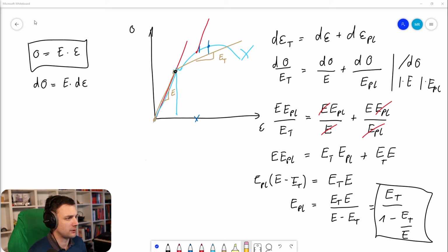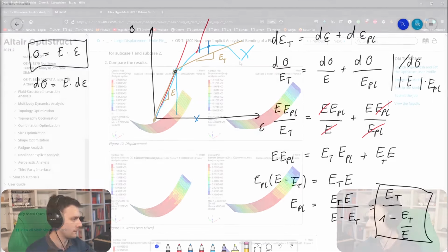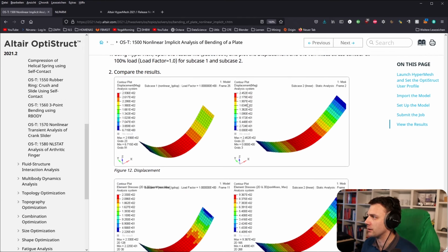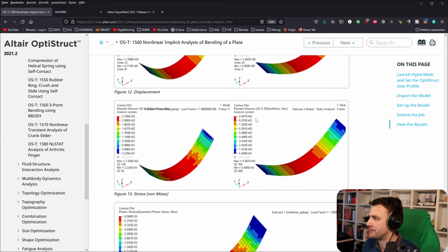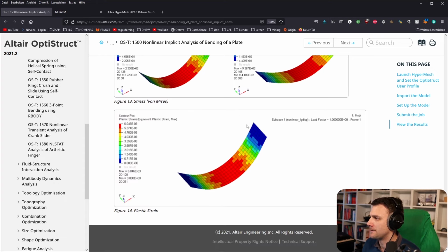All right. Let's look into the tutorial, how they sum up the things here. Now you can see the differences here, and that we indeed built the model correctly. The displacements, you have that 29 millimeters here, 24 millimeters there. Element stresses. And then also what's interesting, the plastic strain, because if you calculate the nonlinear model, what you want to see is not so much the stresses, because it will not exceed the yielding point too much, but rather the plastic strain, and whether it's still acceptable to have higher plastic strains in areas of your interest. So check more for plastic strain, and yeah, that's it.